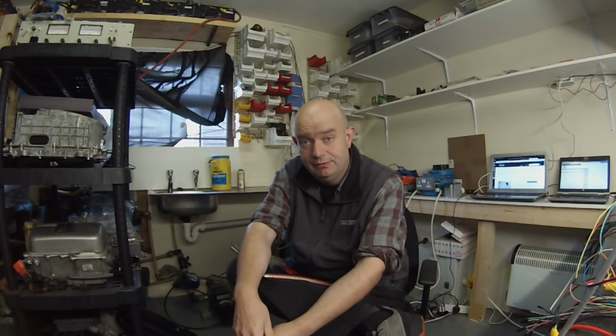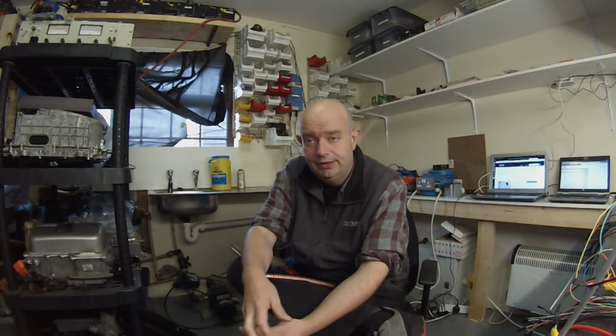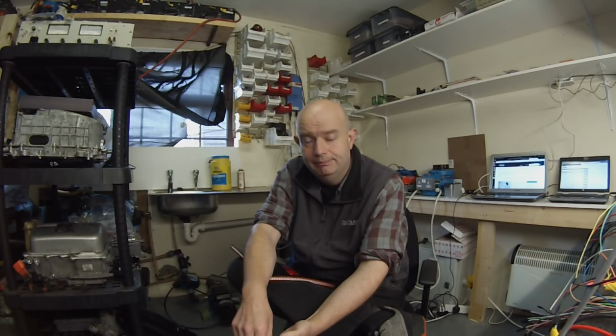Number one was the switching frequency, and the second one that I didn't actually mention because it just sounded a bit crazy, but I think has pretty much turned out to be the cause, is the way that the inverter shuts down on detection of an overcurrent event. So when I got over to Romania, I had brought my own small drive unit inverter, and we went ahead and fitted that to the vehicle.